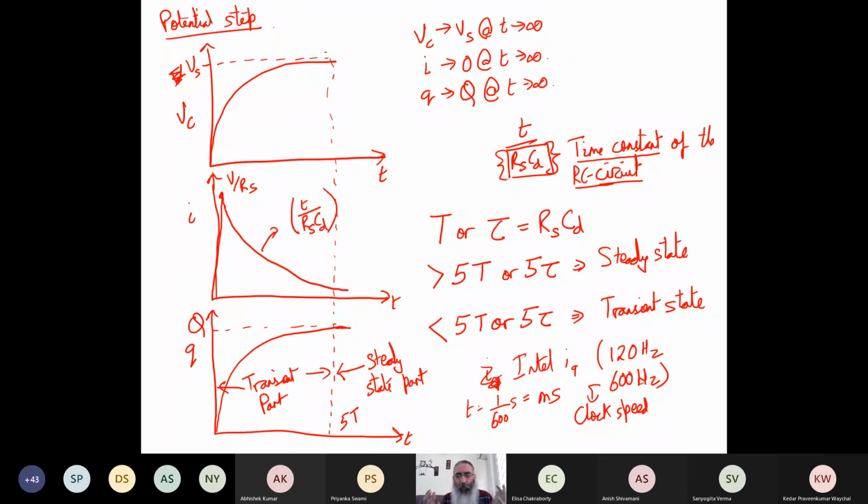So if you want to be extremely precise, you can actually measure a potential between the copper metal and the solder. That potential is because of the work function difference between copper and solder. Once you have a potential, then you will have a junction current. When you go below nanoamperes, these start to become increasingly important. So for example, if you want to measure really small currents, you don't use the lead tin solder that we use. You use a special kind of solder which is made up of indium.